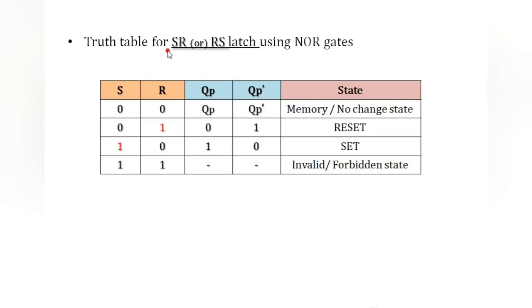Finally, the truth table for SR latch. Observe this truth table. I have drawn all these values by considering the operation output values. First I am taking the 0, 1 condition, that is nothing but the reset condition. This is the output, this is the complement of the output. Reset is active here. Output is 0, so output is reset and complement is 1. Okay, satisfied. 1, 0 condition: output is set to 1 and complement is 0.